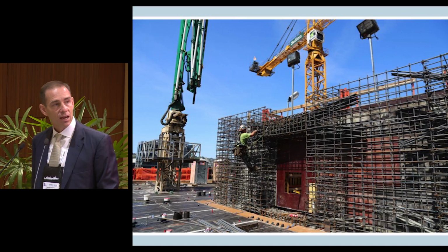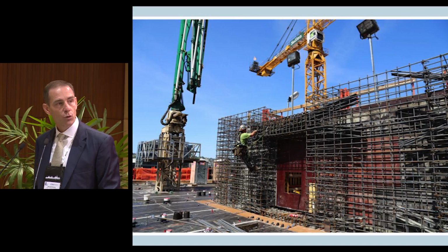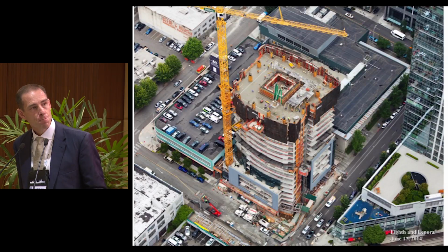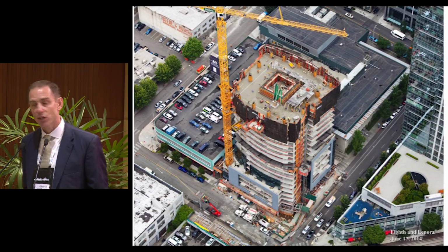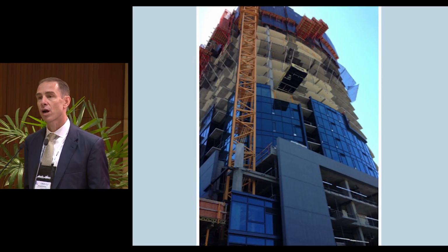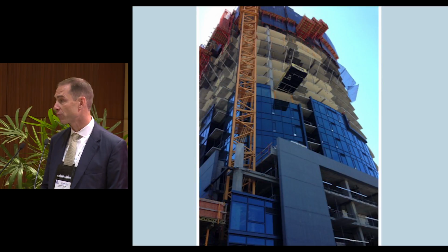Again, it's a performance-based design, ductilely detailed core, so some fairly heavy reinforcement in the core as we're going up. Post-tension concrete flat plates, no beams, perimeter columns. So, to describe the building, it's actually relatively simple above grade. There's really three components: a wall, a plate, and columns.